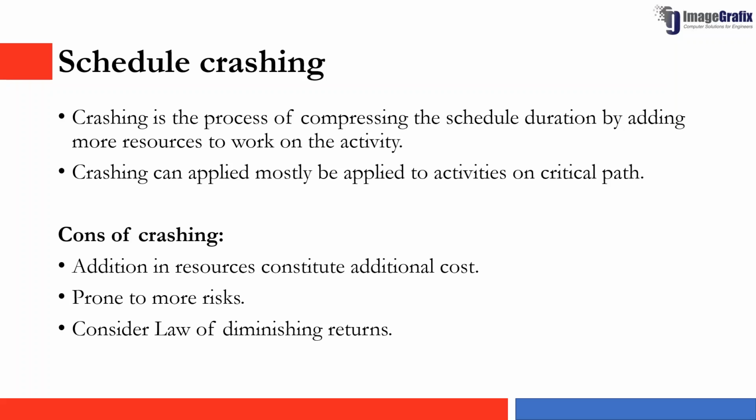And the second consideration here is the project schedule will become prone to more risk because of the involvement of more labor. So currently we might have assigned some proficient resources to work on the particular activities, and in order to reduce the duration of the activity, we might be involving some labor who are less proficient in the particular activity. So we have to see that consideration, and then we have to check the risk that is going to happen on the particular activity just by adding the resources. So this constitutes the learning curve.